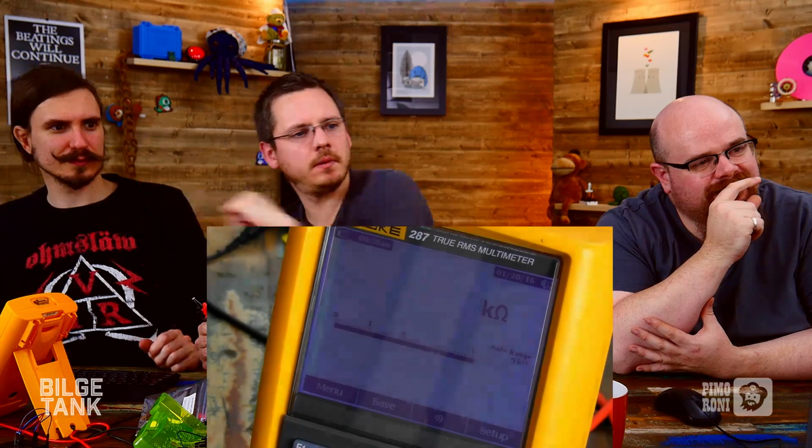So we're reading about 4 kiloohms at the moment. I bet we've got a lot of glare on the screen. Turn the backlight on, maybe. Oh, lovely. So the LDR is currently reading as if it was a 4 kiloohm resistor, give or take. And if I cover it with my finger, it rescales and it's gone up to 17k. It's gone resistive.